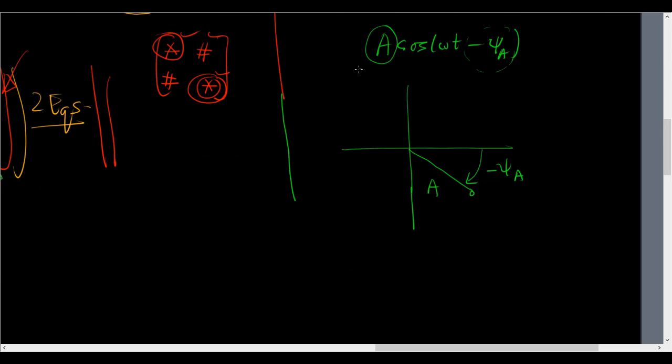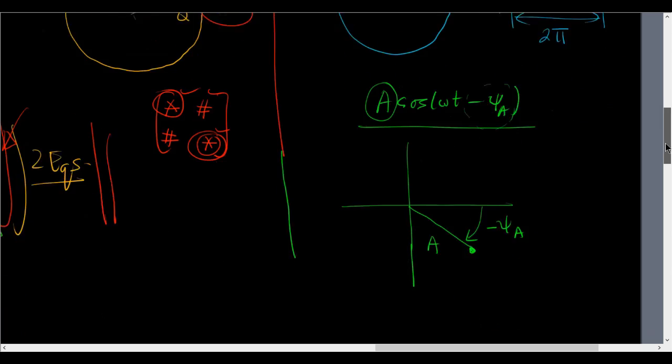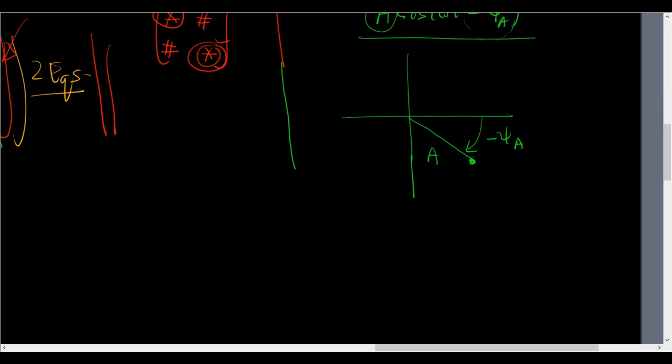This state of vibration without a trial mass is represented like this. Now I add a trial mass, which I will draw in red for you to see. With the trial mass, the vibration state changes. Let us say the vibration state is now this, and this is the change in vibration state.